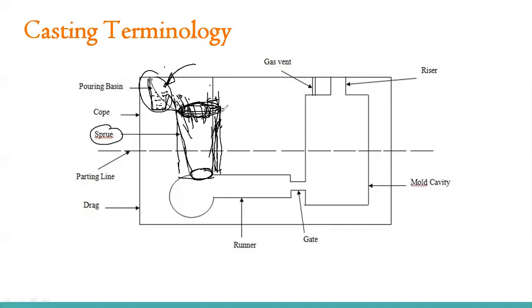Okay, so because of that, once the molten material is moving inside, the gas will also start moving inside along with this molten material. That will form an excessive amount of gases, and the excessive gases reach inside this runner or this mold cavity, which will not be helpful. Another problem is that because of this gas entrapment, again as I said, porosity forms.